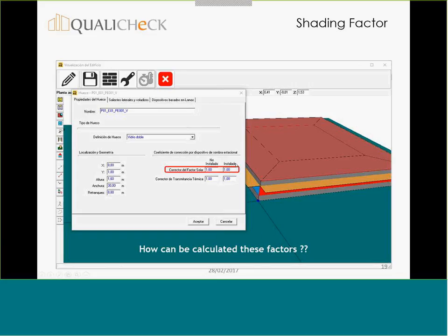So you have to know what type of shade you are using, and then you will put here the name. If you cannot prove that the seasonal value of this shade is correct, you must use 1. I mean, if you put there a number which is not 1, you have to prove that you have calculated somewhere, somehow, the reduction, the shading factor.